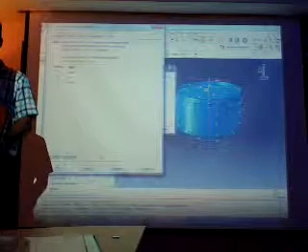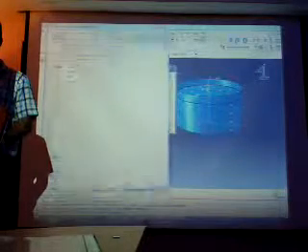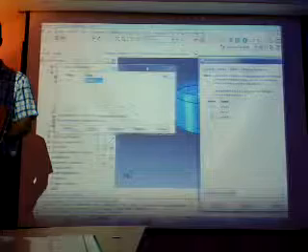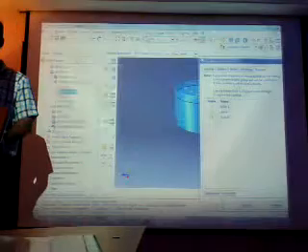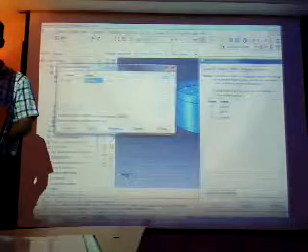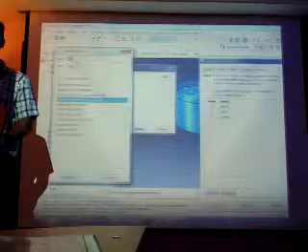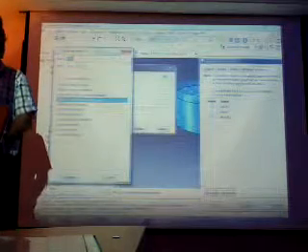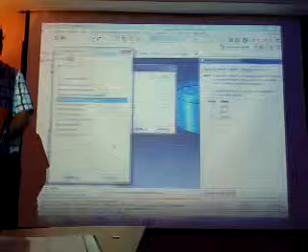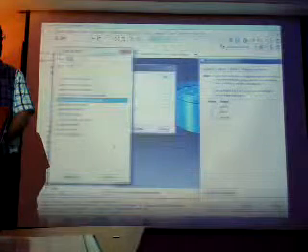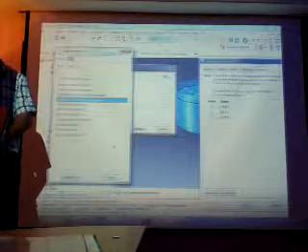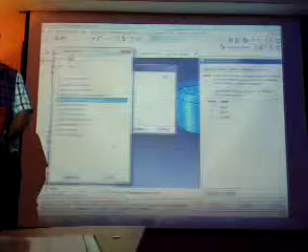Now we have the second interaction between punch and billet. So I hide the die, apply, and create a second interaction, interaction 2. I think you have to make a surface set for the billet first. I mean, create surfaces for the billet.